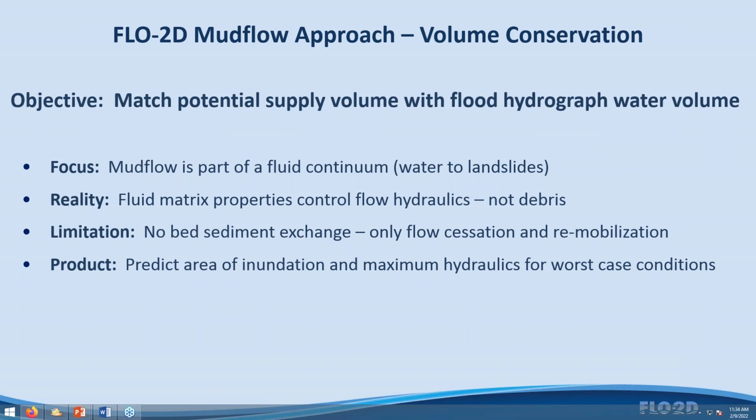Now, we've remedied this limitation to a certain degree with the new two-phase flow component, and I'll discuss that in the fourth webinar. The product of your simulations is basically an area of inundation, and what you'll use out of that is the maximum hydraulics, and you'll try to create a worst case scenario for flow depths and an area of inundation. But again, there's a range of conditions that this applies to, so you have to be cognizant of that.